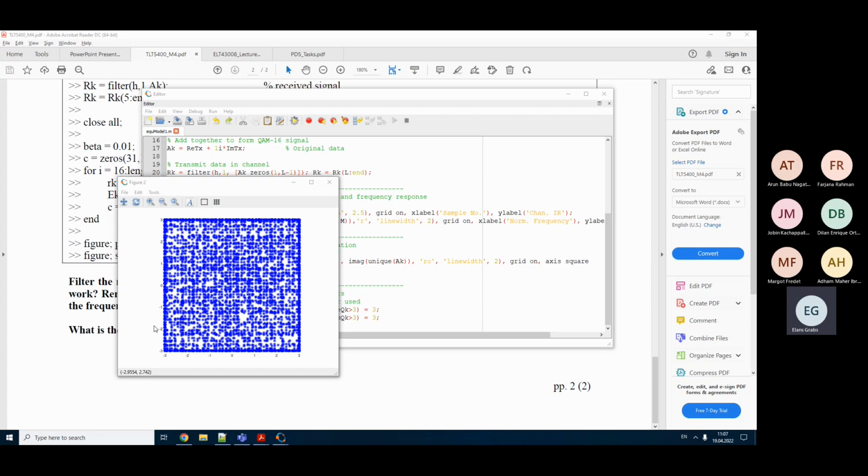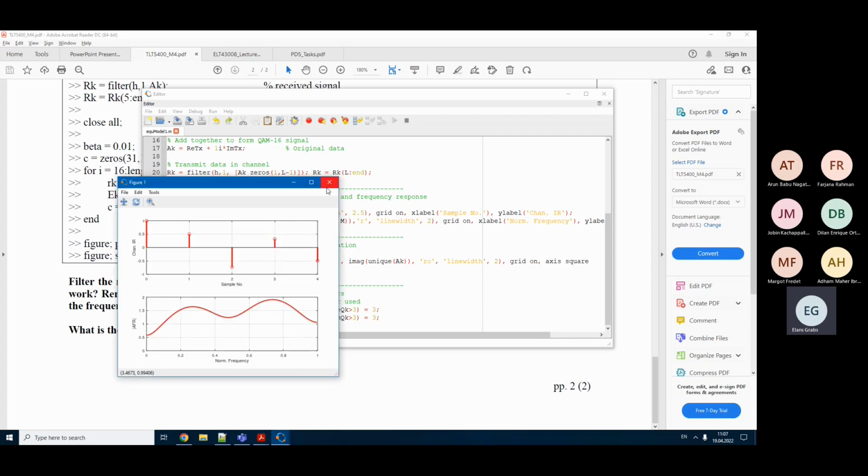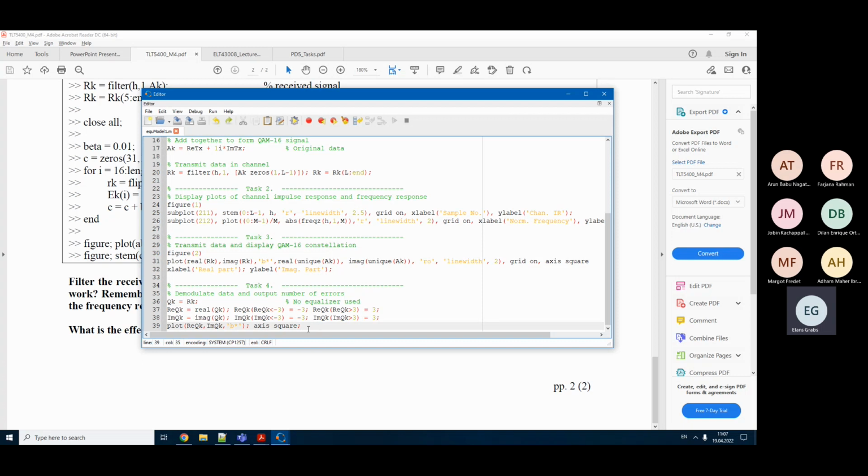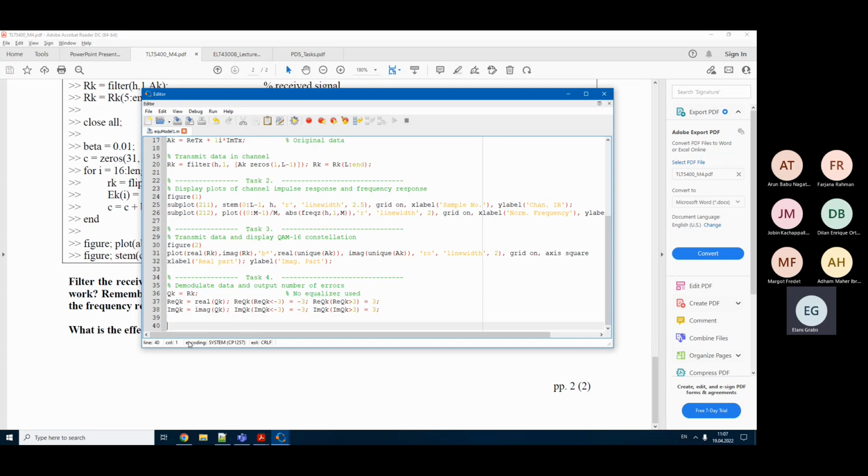So what we want to do next is to actually demodulate it. However, thanks to this fact that now we have these numbers in this range, we can simply round them. Yes, so here I'm going to offer you this simplified detector, which operates very fast and doesn't use much memory. And basically we can detect QAM-16 symbols by rounding.